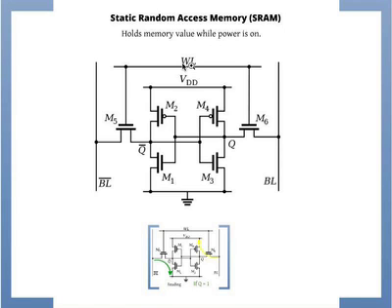So let's see what this means first of all. Before we look at the transistors, first of all, we have what's called a word line here. So this is row-column addressing for memory. You have basically a grid. So you address one row. You have what I call bit lines, and you have what I call word lines. If you pick this, and let's say you pick that, then you read that thing out. And so that way you can pick out any grid. So that's the basic architecture.